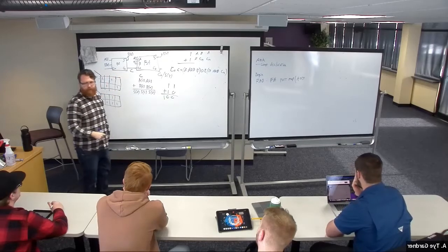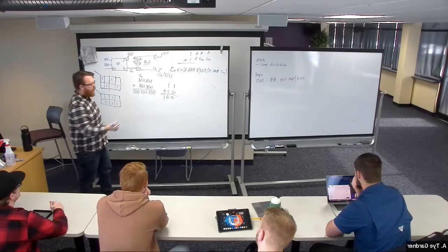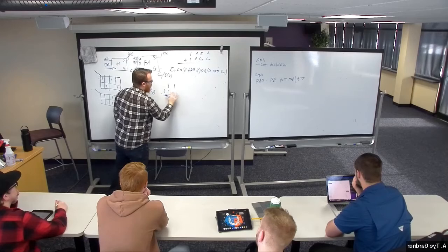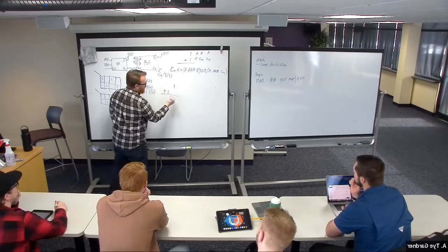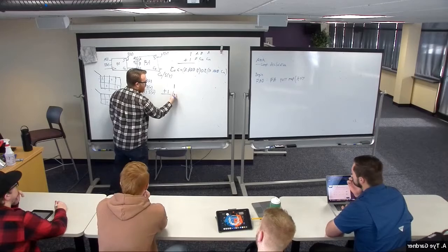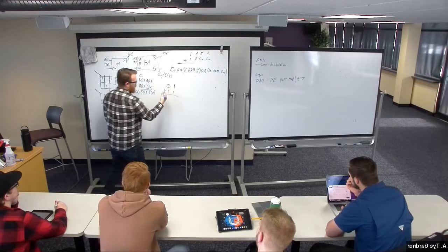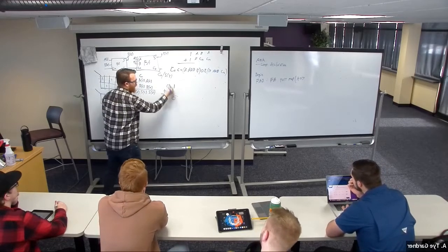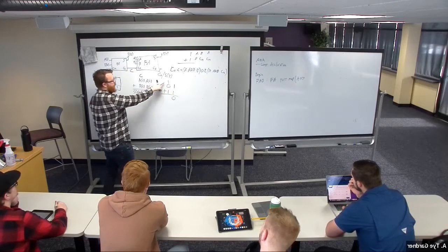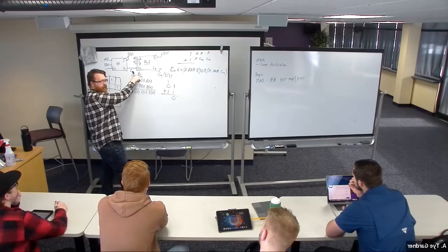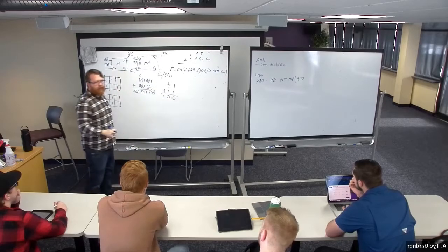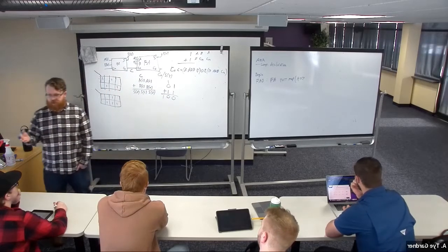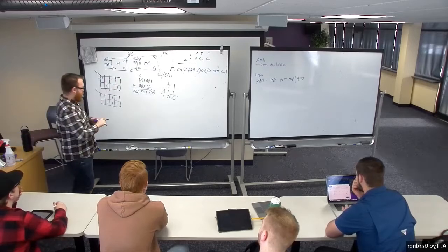That would be my sum. Similarly, yeah, 1, 0, 1, sorry. Let's say I have this addition. Now it's 0 with a carry. That carry is now 1, which the carry in sees. And now it does 1 plus 1, which is 0 with carry. Right? That's all this is doing. You just write the code one time.